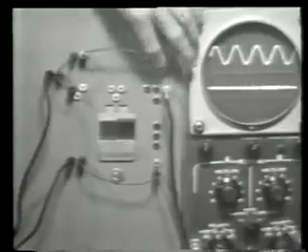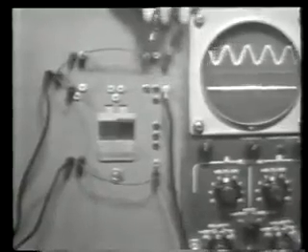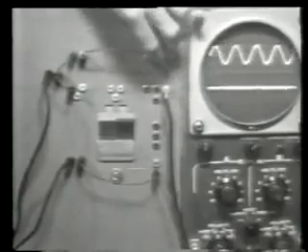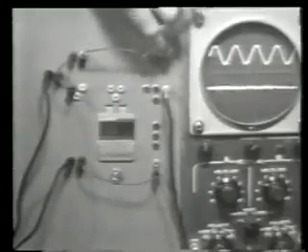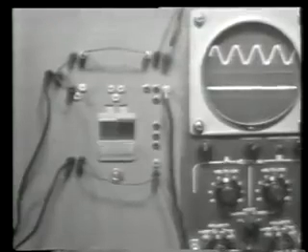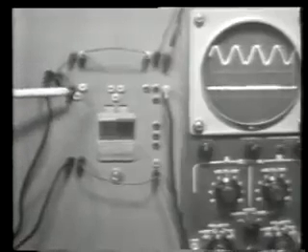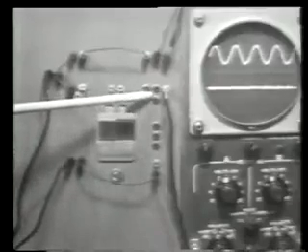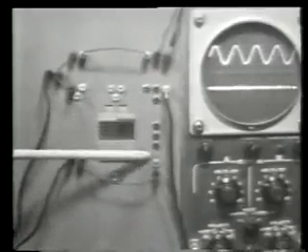Now the middle connector here is used to provide a synchronization voltage for our oscilloscope, which as you can see we need. I'll just plug that back in. That's the top trace. Remember, it always displays the output directly from our signal generator. Now the lower connection here, this is where we'll connect our filter components. The series component here, the shunt component here.